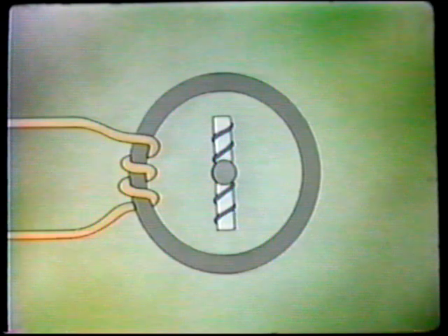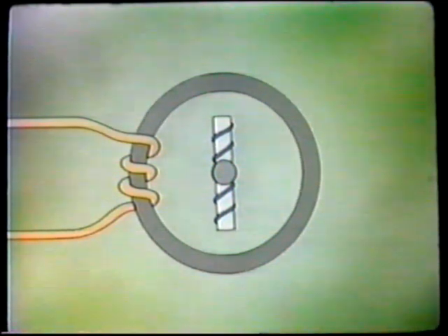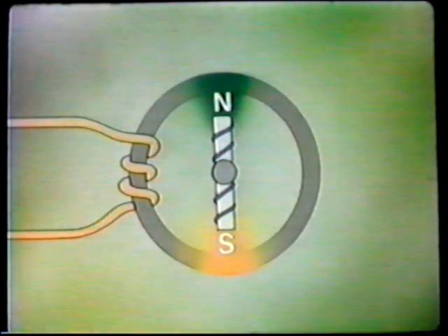Let's energize the electromagnet. Direct current now flows through the rotor, creating a magnetic field around it, the first of our three requirements for induction. As in any magnet, there's a north pole and a south pole. We'll use green to show the north pole of the magnet and yellow to show the south pole. The coil around the core is a conductor, which is the second requirement for induction. The third requirement for induction, relative motion, occurs when we rotate the electromagnet.